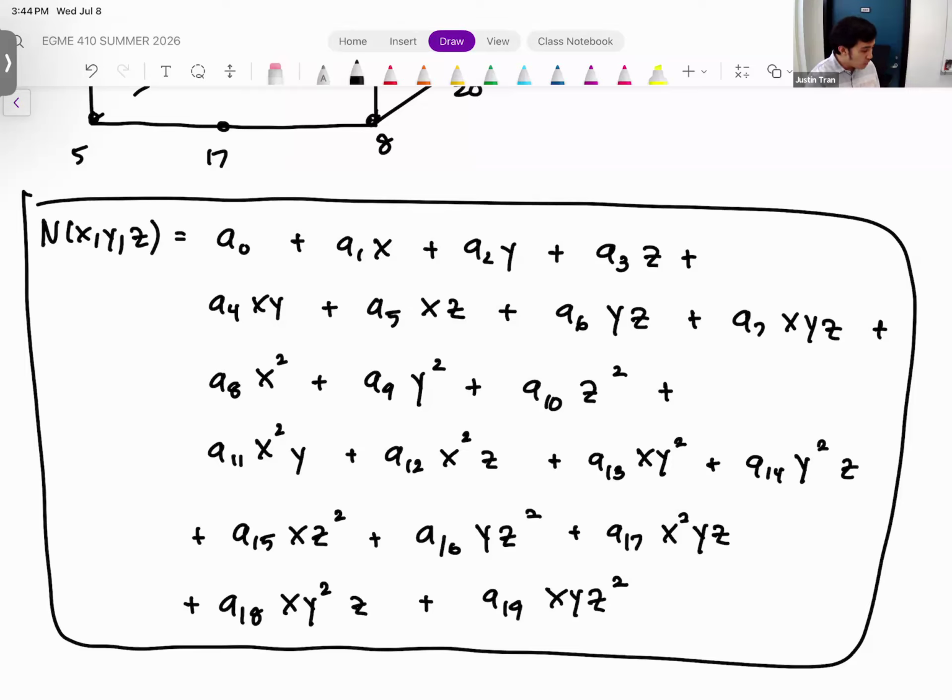All right, any questions on the quadratic hexahedron? Okay, good. Before we end our discussion here, I do want to make a quick table, because we've covered 2 dimensions of element decision making. You have to make a decision in terms of the element shape, and you have to make a decision in terms of the element order. So I have this nice handy table, which summarizes everything that we've talked about in terms of their properties. If you do have to make a decision, this table can help you choose which one makes the most sense for your situation.